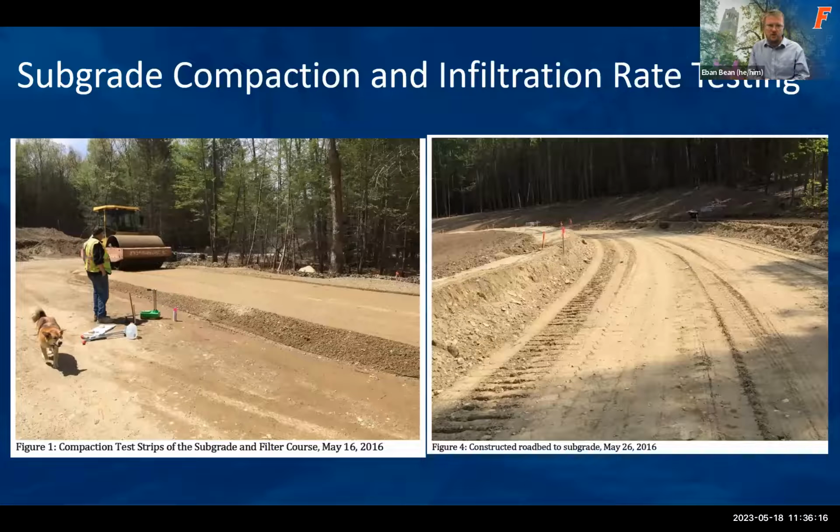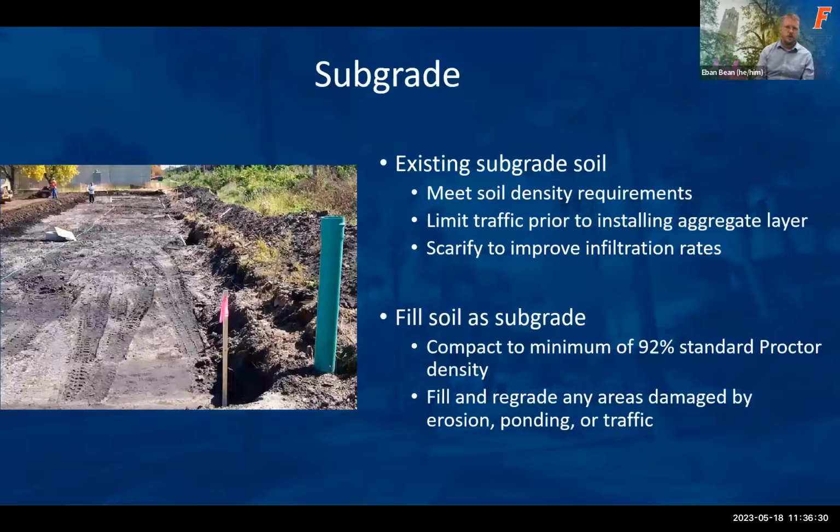So we do want to make sure that our soils, our subgrade, is structurally sound, but we want to avoid having it be over-compacted to where we are limiting our recovery of the volume. The existing soil grade, we want to make sure that this meets our density requirements. So oftentimes we're going to have some percentage of the standard Proctor density to meet.